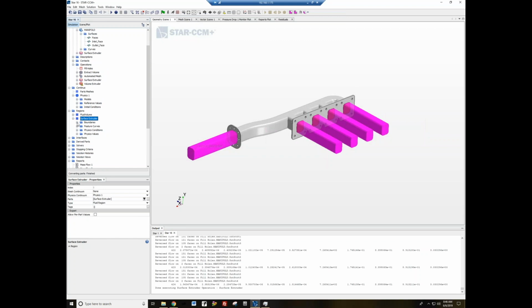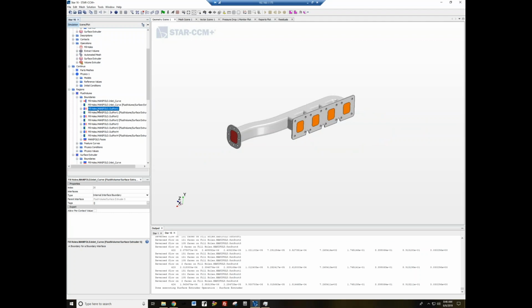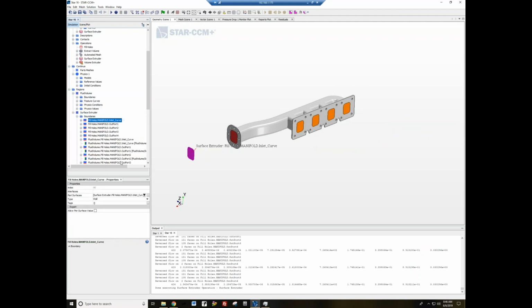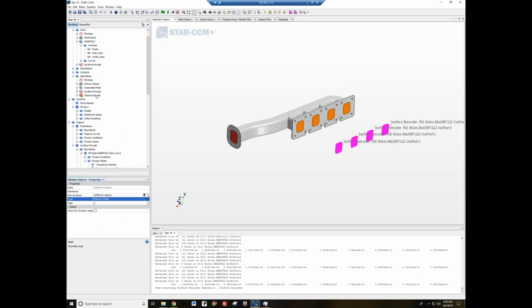Now, one thing to bring to mind is if we look at our original region where we had these boundary conditions defined before, they're now masked over by the interface constraint. We actually have to assign our boundaries at the new extensions that we created. We do have to reset this boundary and make it, I think it was 2 meters per second that we had before, and then these 4 just become our outlet pressure conditions.